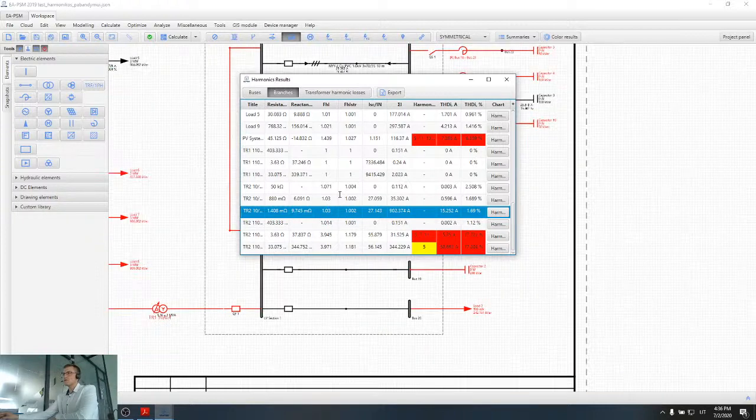So basically this FHL factor is 1.03. In order to calculate losses in the transformer, I take the losses created by the 50 Hz current and multiply by 1.03. This adds 3%, so not too much. Stray losses are even less affected by the harmonics, only by 0.2%.